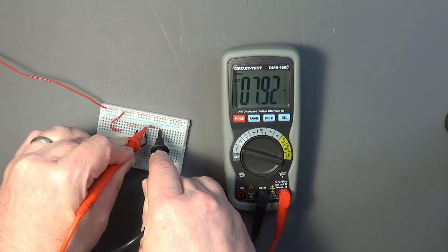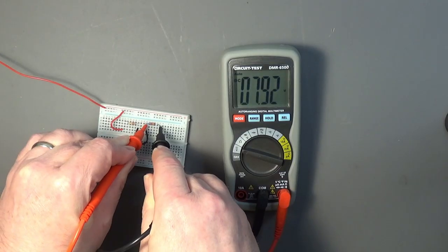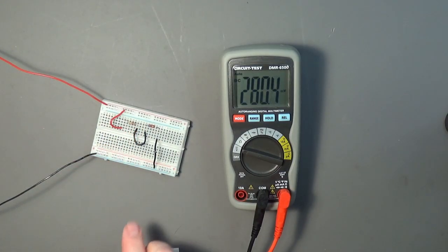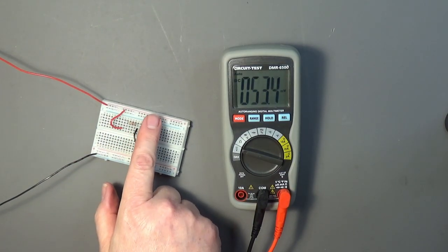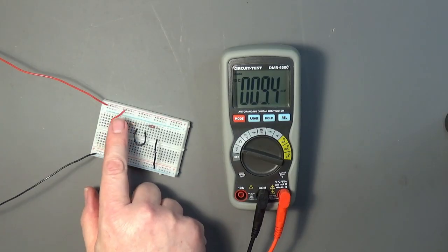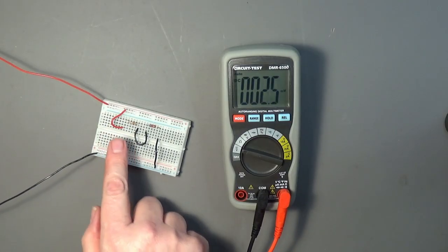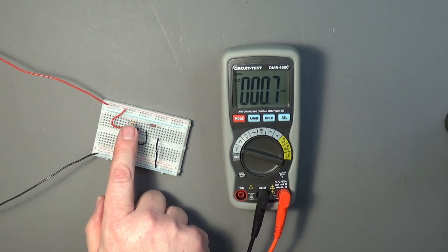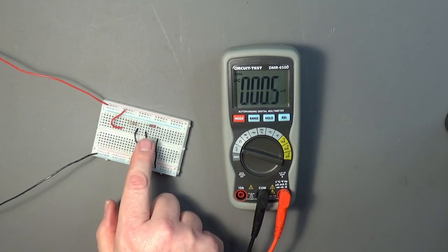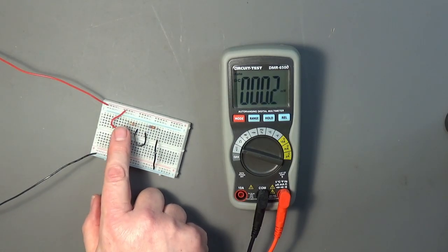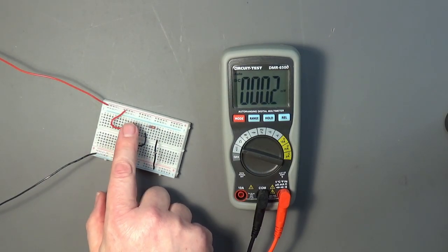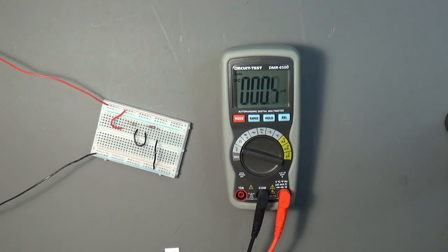So basically it's in proportion to the size of the resistors. The larger resistor has a bigger change in voltage across it. That's called a voltage drop. So the voltage drop across this 1K resistor is smaller than the voltage drop across the 6.8K resistor. And if we add those two numbers up, we should get the total of 9 volts again.